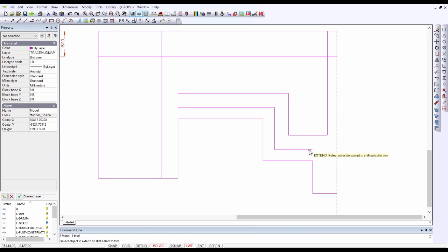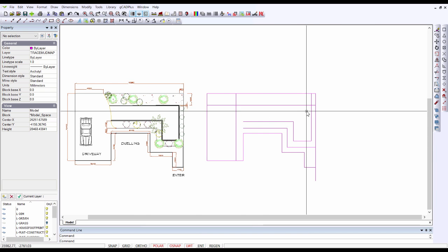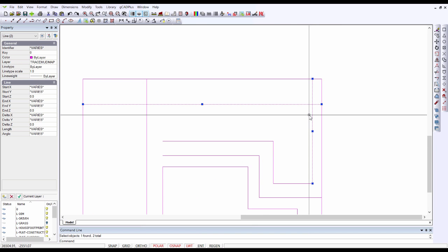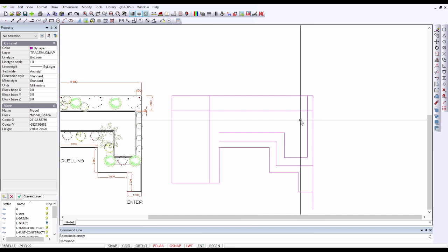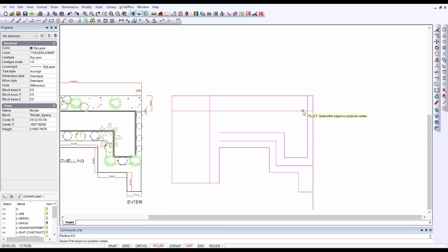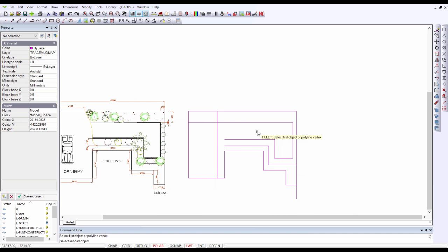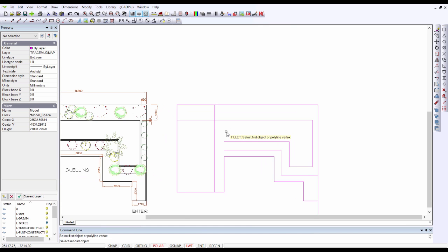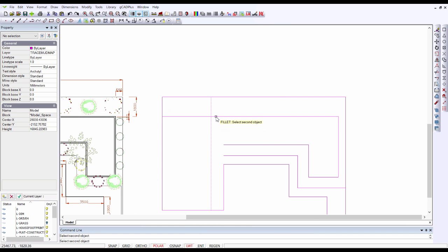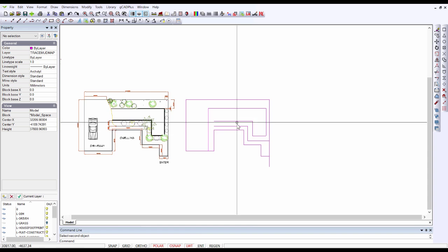This is the boundary, and we can extend that path through there. So we've got pretty much our shape, although we need to work on this area through here. You might like to try the fillet command. Modify fillet, and if we pick these two lines, you have to be a little careful about where you pick: past the midpoint of the line, that's fine there, and then past the midpoint of this line, and we get a squared off trim in one action. You could do the same here and trim, and there we have our shape nicely defined.